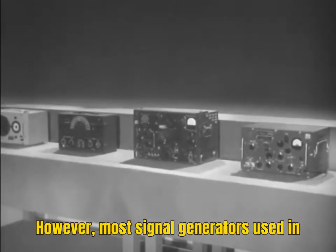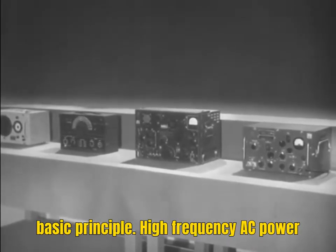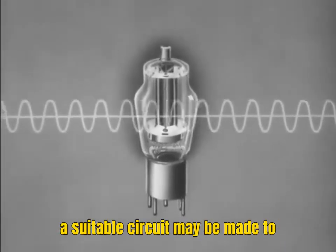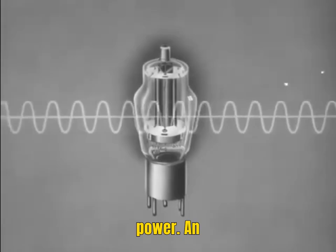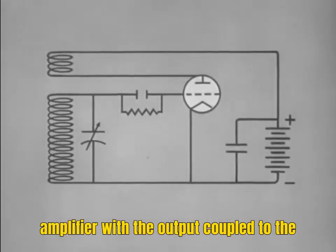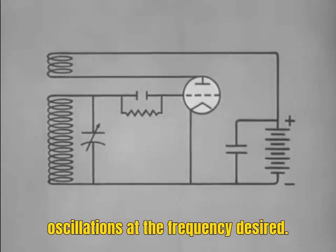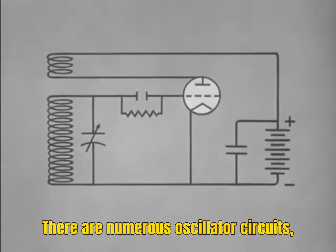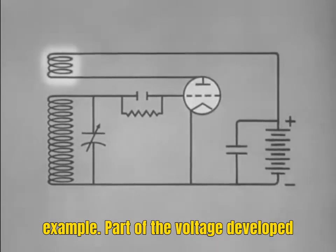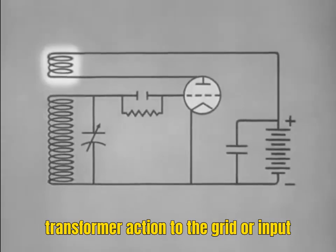However, most signal generators used in communication work operate on the same basic principle. High-frequency AC power produces the signal. A vacuum tube in a suitable circuit may be made to oscillate and generate high-frequency AC power. An oscillator is simply a vacuum tube amplifier with the output coupled to the input in order to generate or sustain oscillations at the frequency desired. There are numerous oscillator circuits, of which this regenerative circuit is one example. Part of the voltage developed in the output circuit is fed back by transformer action to the grid or input circuit.